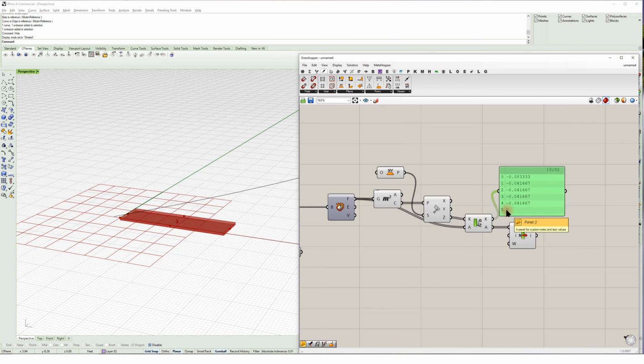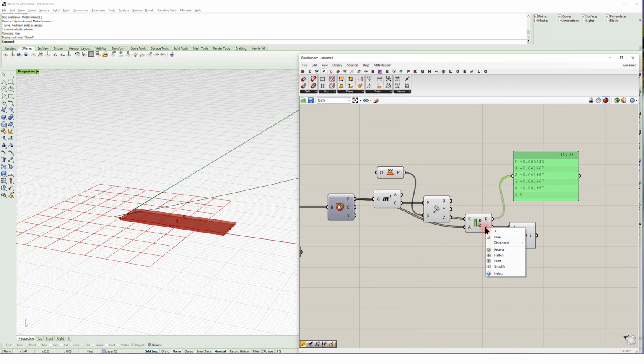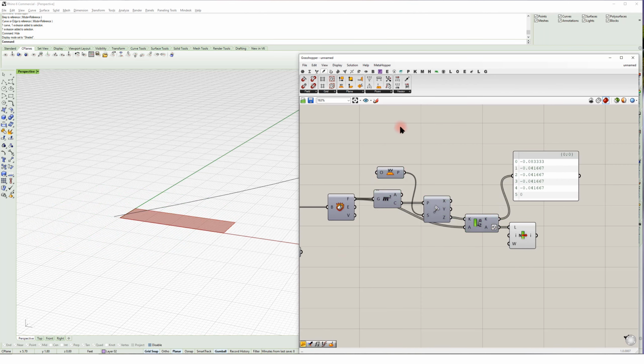One is 0 distance away from that coordinate system. That's the highest point. That's actually the one I want, which happens to sort to the very end. So all I have to do is reverse this list by right-clicking, reverse the list. Now if I select, it's got that topmost face. Perfect. So I'm just going to select all this and hide that and delete that.